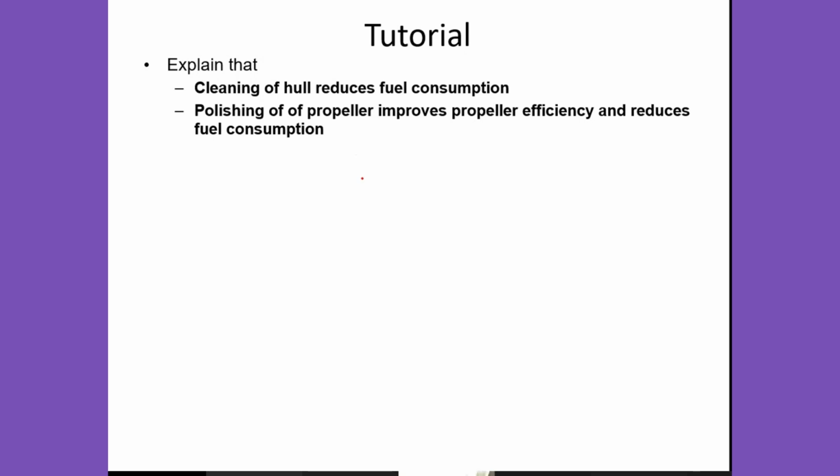There is something called total resistance. If you see here, this is the total resistance of the vessel. Let us say this is a vessel, and here we have the propeller. The vessel moves because a thrust is created by the main engine, located somewhere here. The power is transferred to the propeller, which creates a thrust, and the thrust power is thrust into the speed.